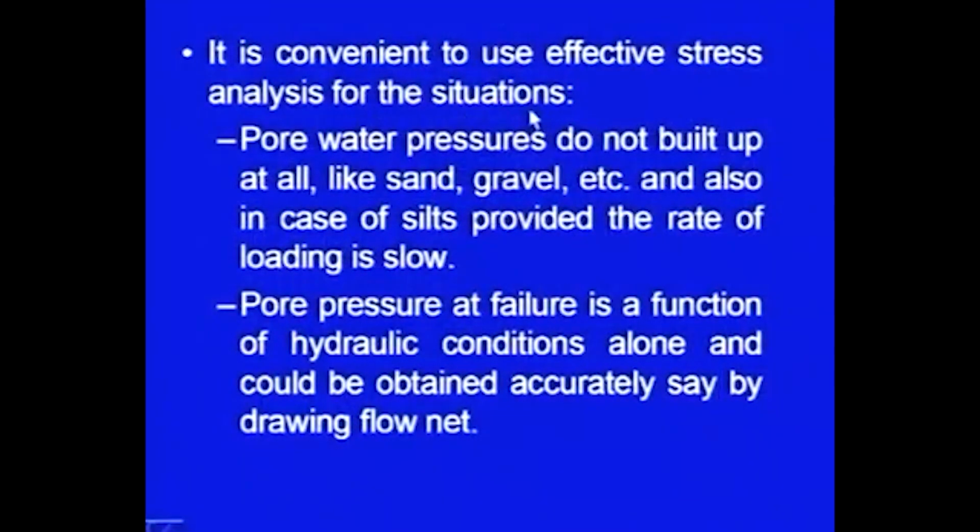It is convenient to use effective stress analysis for the situations, number 1, where pore water pressure does not build up at all. So, for example, if you take sand, gravel, and maybe in some cases the silts also, if the pore water pressure is not developing, then effective stress analysis should be used. It all depends on the rate of application of the load and also the rate of dissipation of pore water pressure.